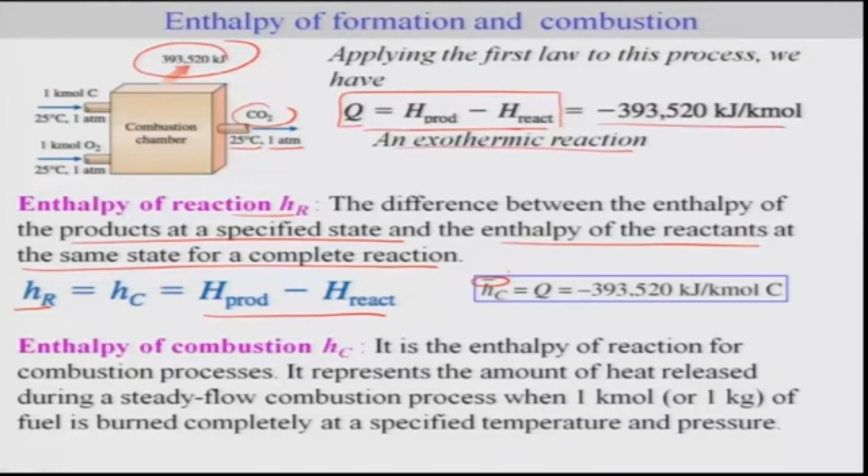The other term which we are going to make use of is called enthalpy of combustion. It is the enthalpy of reaction for combustion processes, as in this case. It represents the amount of heat released during a steady flow combustion process where 1 kilomole or 1 kg of fuel is burned completely at a specified temperature and pressure.